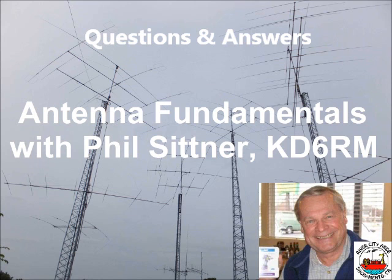A coaxial transmission line is actually an impedance transformer. If the antenna is 50 ohms and you run a piece of feed line to it, and it's a 50 ohm feed line, it'll measure exactly what the antenna is. But if the antenna is 96 ohms and it's either too long or too short, and you put a piece of feed line on it, the measurement you get at the end of the feed line is not what's at the antenna.